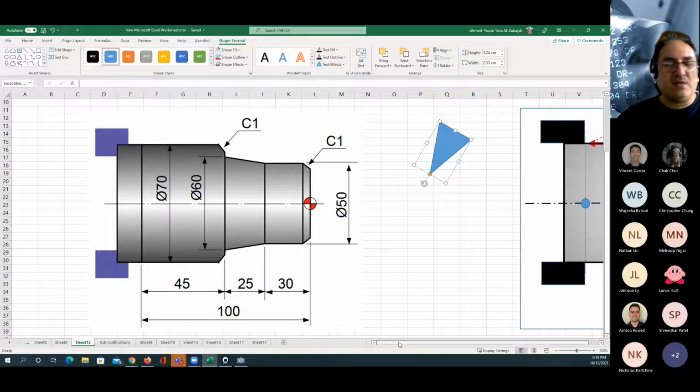Let's say 2.5 millimeters. If I'm cutting steel, I will go anything below 2 millimeters. Things will be different. If my cutting tool is carbide insert, I can go deeper than if I have the high-speed steel. First, because I can do the cut at a faster rate, because the material is stronger.